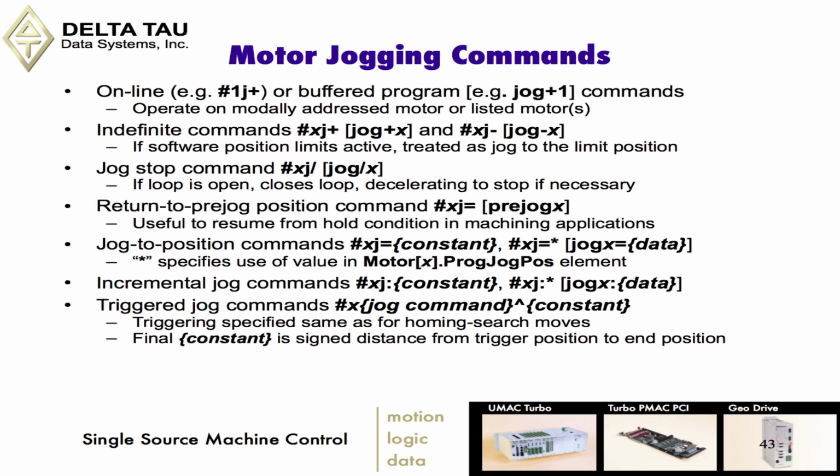Some of the motor jogging commands. An online motor jogging command, #1J+, or a buffered one inside of a motion program or PLC. We could say jog +1, jog +2. And these operate on the modally addressed motors or listed motors, so we can provide a list.